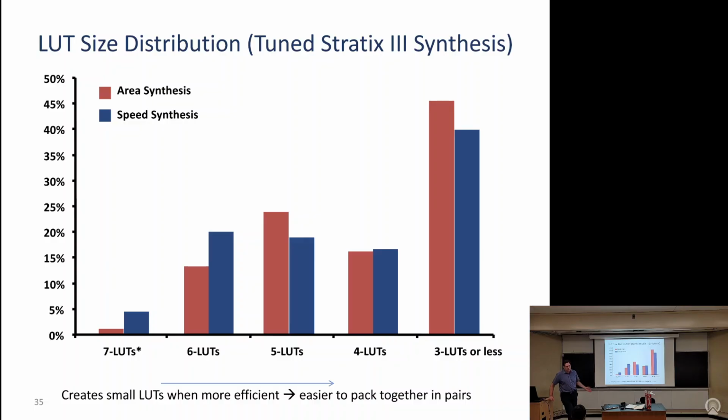You send both data inputs into that logic block. You send the select input into that logic block, and you program the LUTs in there to basically do a muxing function. Does that make sense? Yeah, that makes sense. There are actually a bunch of papers where this drives people a little crazy. They're like, I'm surrounded by muxes and crossbars, yet I cannot use them for all these muxes and crossbars in my designs.